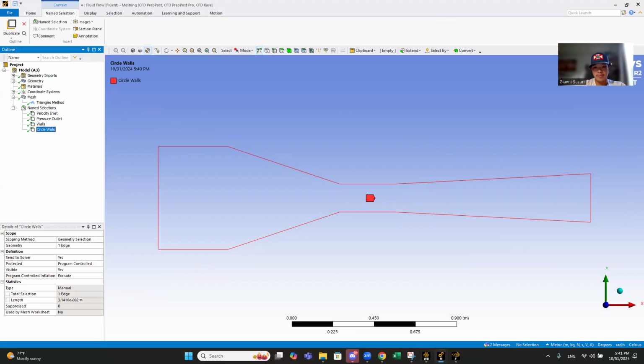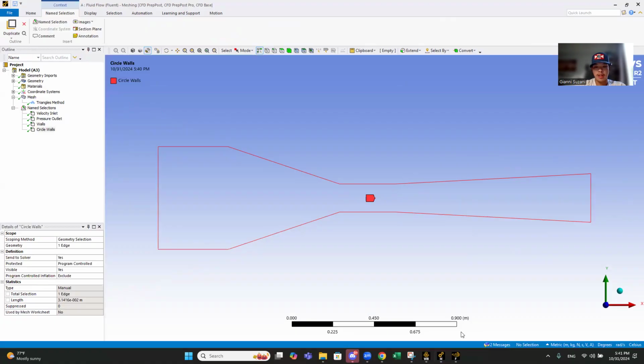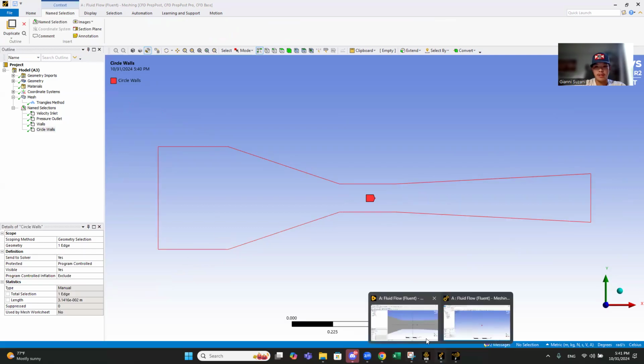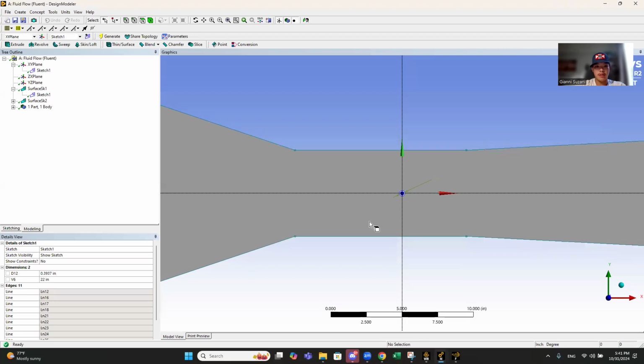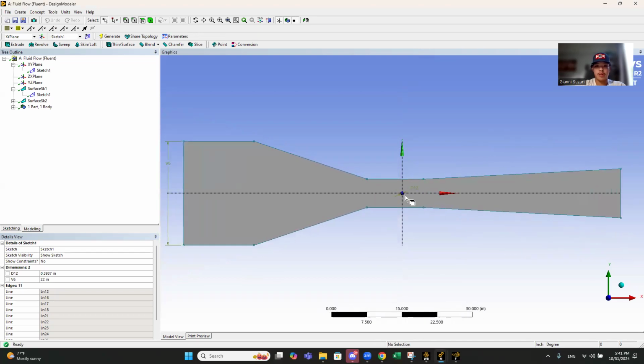After that, you go to your mesh. It's here. This is actually your mesh, and then you should go to here to design your wind tunnel and circular cylinder right here. When you convert 10 millimeters into inches, you should get 0.3937 inch as your diameter.